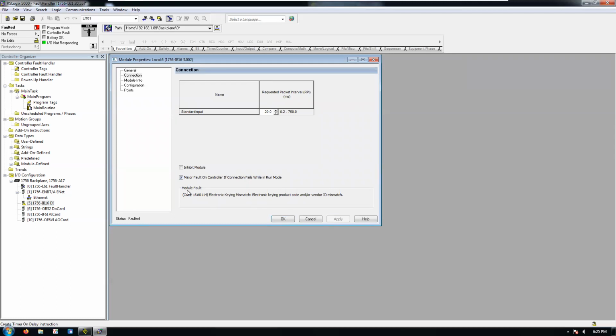So if you have a faulty card and you have access to spare cards, swap the card out to something that's working. If it's 3 weeks to order one in because the supply chain is screwed up right now, for example, I think we are 32 weeks out on a VFD for a capital project. That's most of a year. So if you don't have spares on your shelf right now, you could have to fight fires and band-aid things like writing this fault recovery logic.